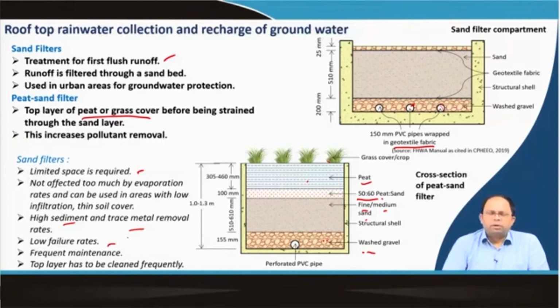As for failure, these are pretty robust, they work pretty well, they do not fail too much, but they require frequent maintenance. You have to clean the sand to remove the dirt and sediment that gets captured into it, and particularly the top layer has to be cleaned frequently.